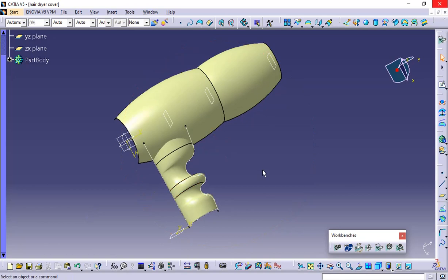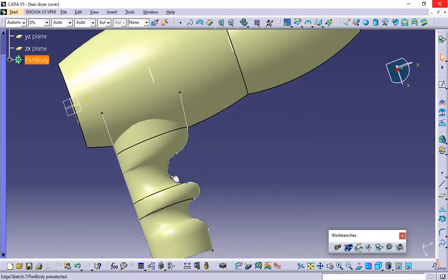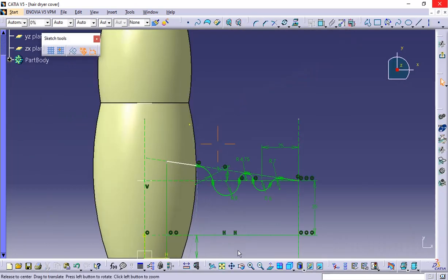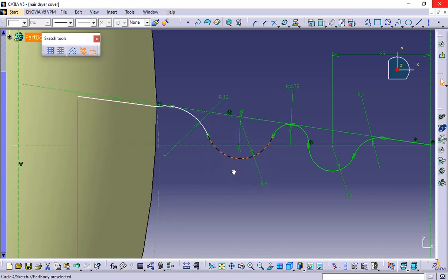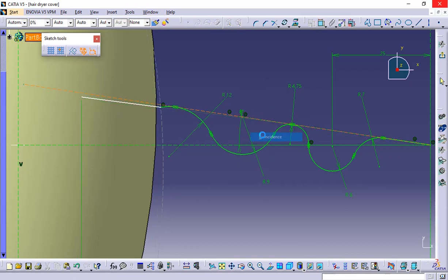So if you feel that the curvature is too much inside, then you can just select this curve and here remove this and just move inside a little, or just select this taper line in the center curve and just make them constants,